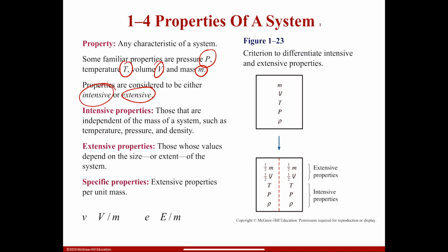When you are working with engineering machines, right? If you want to know that the machine is working properly, for example, you have a pump, right? And you check the pressure at the exit of the pump and the pressure is not what you expected, then you can determine that the pump is not working properly. Therefore, you get into the engineering device, fix it, and measure the pressure one more time until you get the pressure that is needed for the whole system.